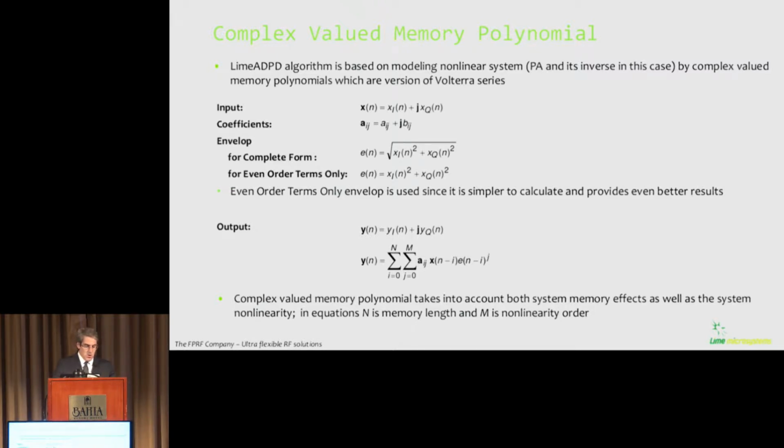So the complex valued memory polynomial model takes into account both system nonlinearity effects as well as memory effects. As you can see in the equations at the bottom, n denotes memory length and m denotes nonlinearity order.